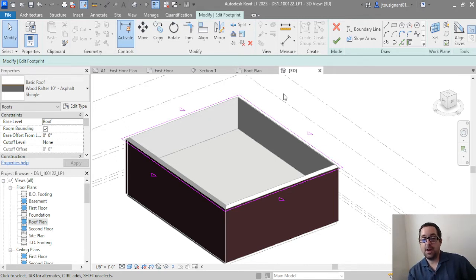Now, when I double click on families, it goes into the edit type properties. So not only is it not a hindrance, having to go into the edit family and then close it and say don't save, it can actually be a tool to save me a couple seconds if I get used to it. I haven't opened the edit properties that way yet.